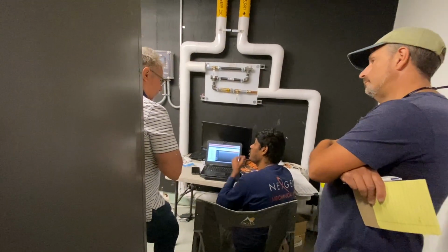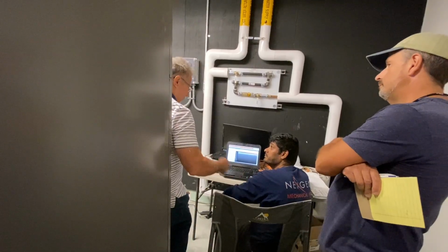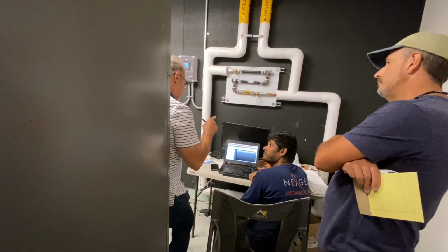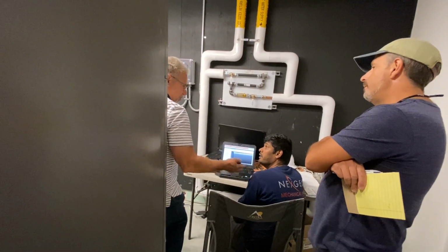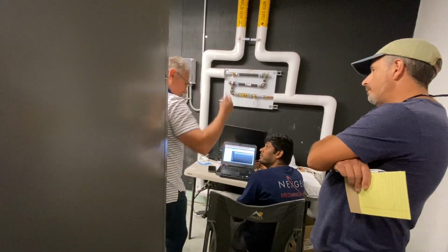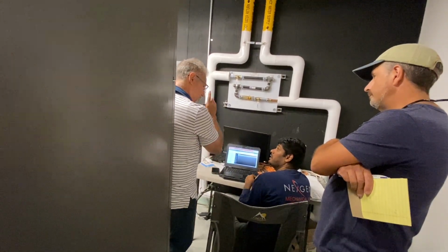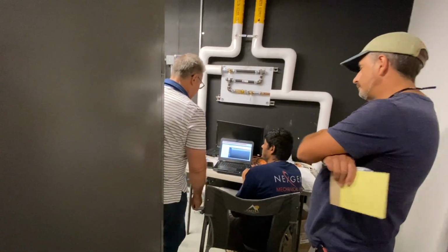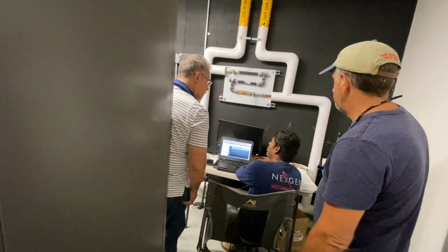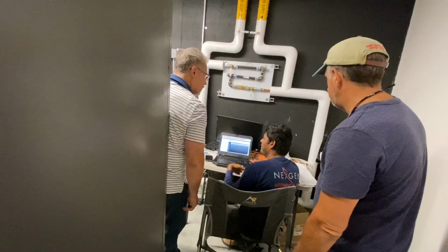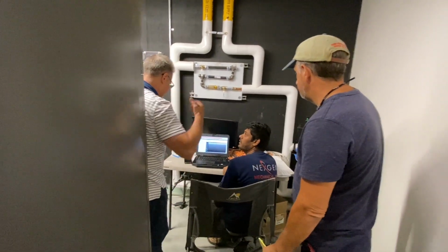We can change it. It can go to a standby mode, so that's customizable. We'll talk about it, but I don't know if we want walk-ins to bypass anything. It's going to look for X amount anyway, right? It's not going to start the unit until X amount of rooms are occupied, not one individual room. Exactly. You can configure that percentage. You can put it at 100%, so the unit will never go to occupied mode until all the VAVs under that unit go to occupied mode. Or a percentage, 50%, whatever. Exactly.